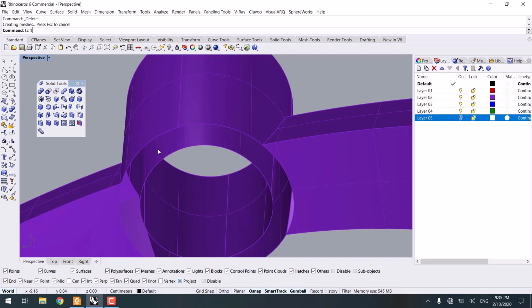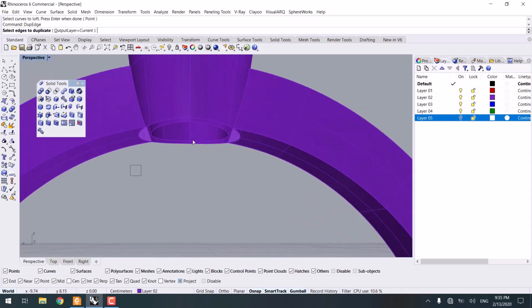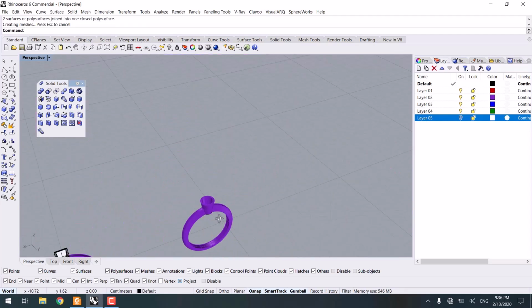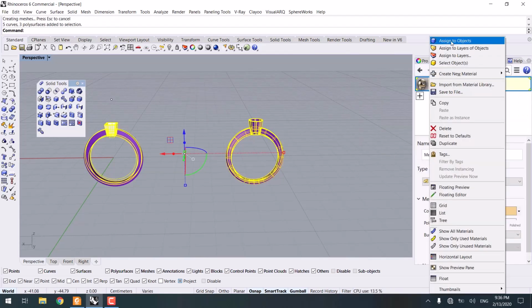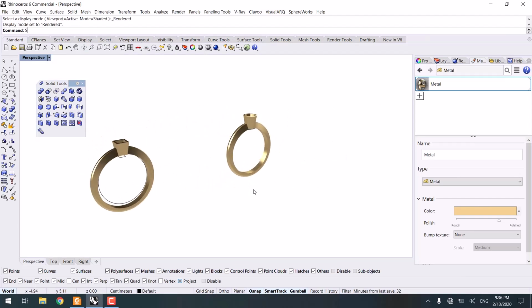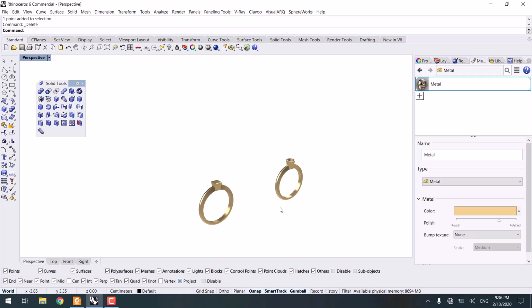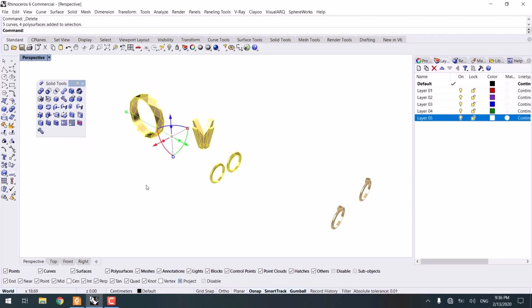And then regarding this opening, we can use a command such as loft to close it down. First off, I'm going to activate Drop Edge, then Join, and after that, I can use Loft. And then at the end, join everything. And as always, now we can add other materials and check the end result in rendering mode, as you can see. Okay, now select curve, remove, and also select point, remove again. And I guess we are all done here.